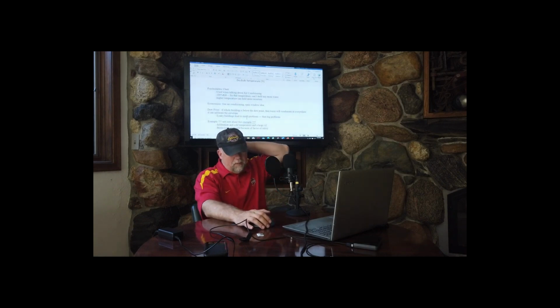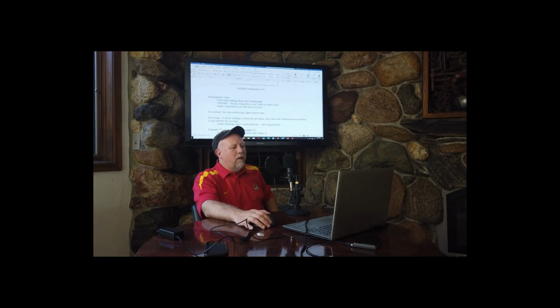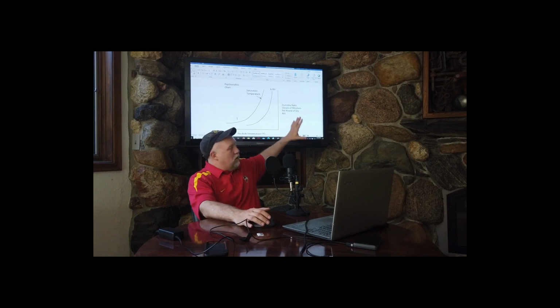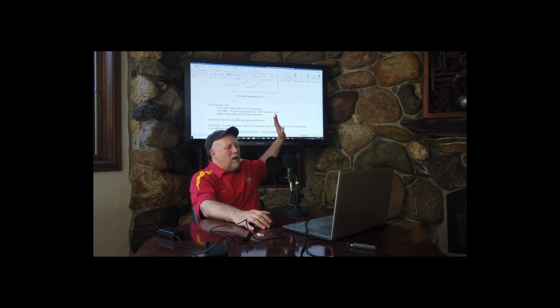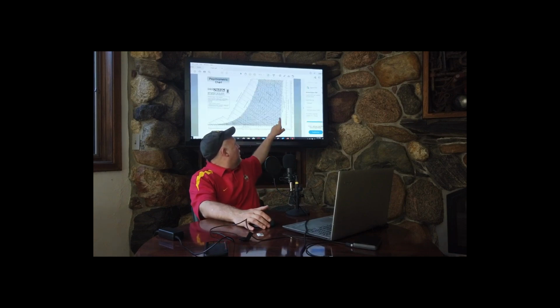All right, couple of terms that we've already talked about, but I want to stress, if we go all the way out to the right on this, we'll look at this in just a second, but there's other information out here, not just humidity ratio and grains of moisture, but there's also going to list like dew point temperature and vapor pressure. Right? Those are all things that are also on the chart. If we flip over to the chart, okay, that's what these are right here. Humidity ratio, grains of moisture, and then right here is dew point temperature, and then this is vapor pressure.